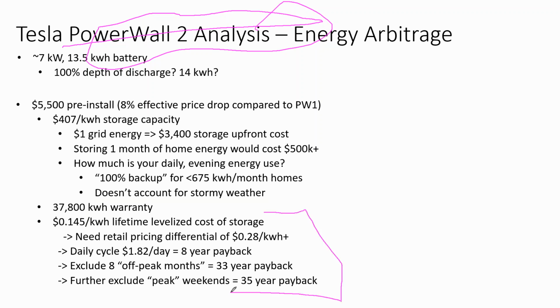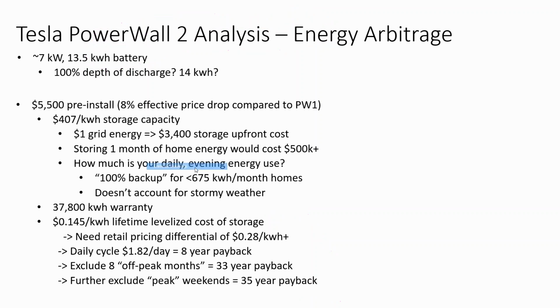But it basically just says that unless you're in a market where you have a daily time of day differential of 28 cents or more, using your battery to day trade electricity is not worth it. It would be better to sell back to the grid at avoided cost than to day trade electricity with your solar battery in most cases for residential type rate structures.